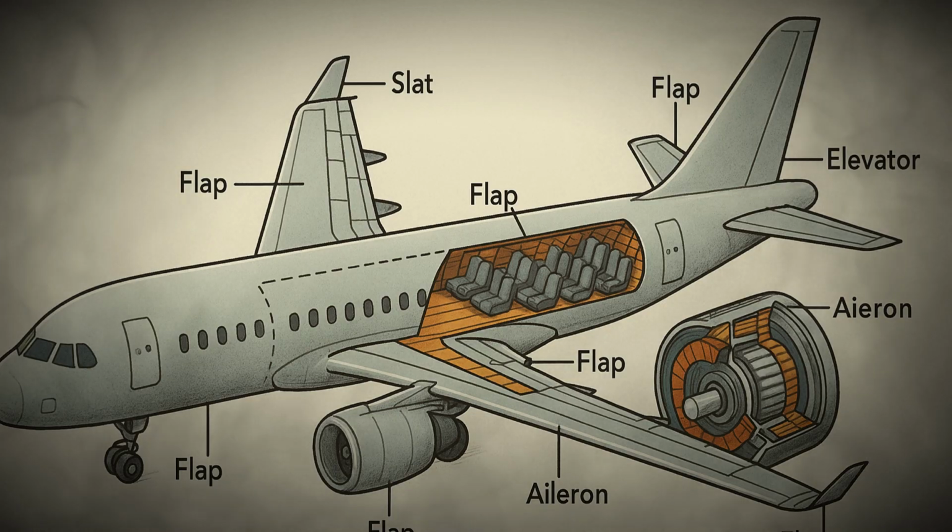In the field of military aviation, afterburning turbojets and turbofans are used to achieve supersonic speeds. An afterburner injects additional fuel into the exhaust stream behind the turbine, producing a dramatic increase in thrust, but at the cost of very high fuel consumption. These engines provide the performance necessary for fighter jets and interceptors, but are not practical for commercial aircraft.